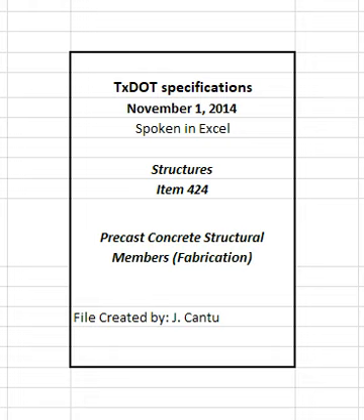4.2.5.2 Placing concrete in hot weather. Keep concrete at or below 95 degrees Fahrenheit at time of placement in accordance with section 424.4.2.5, placing concrete. Use any of the following methods, as needed, to control the concrete placement temperature.